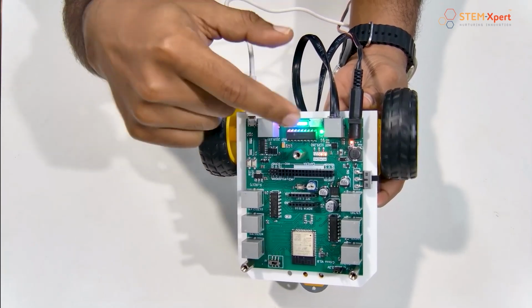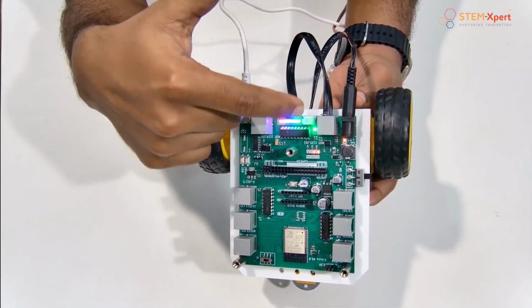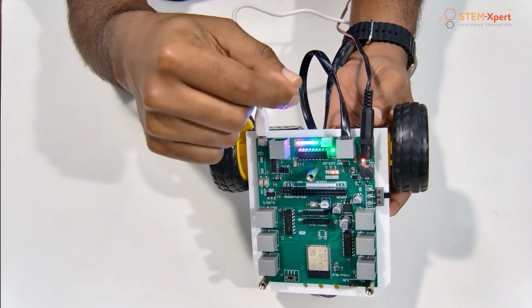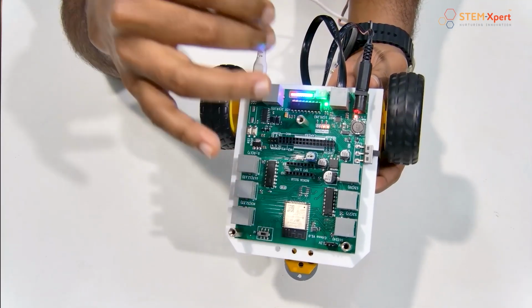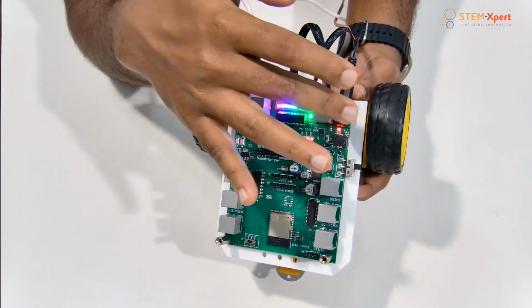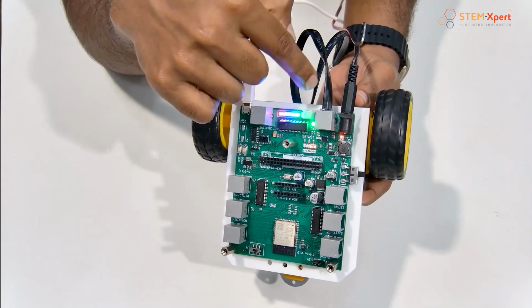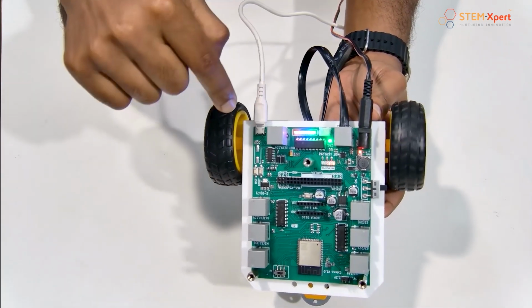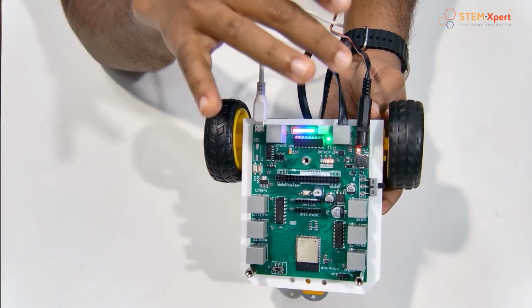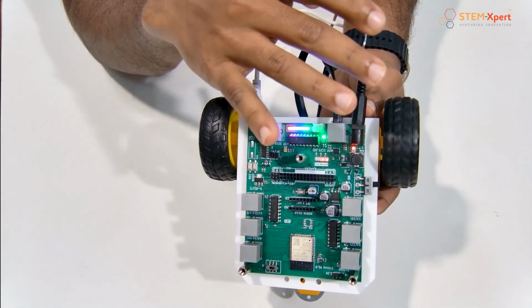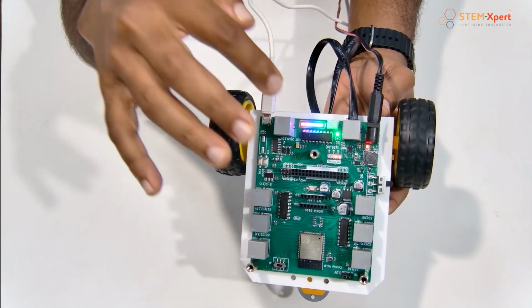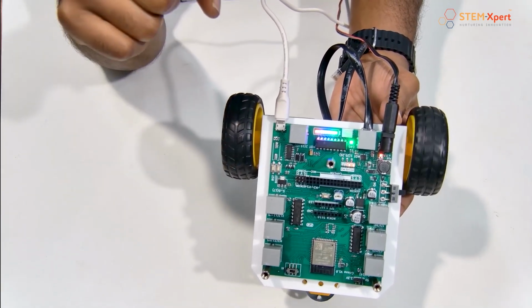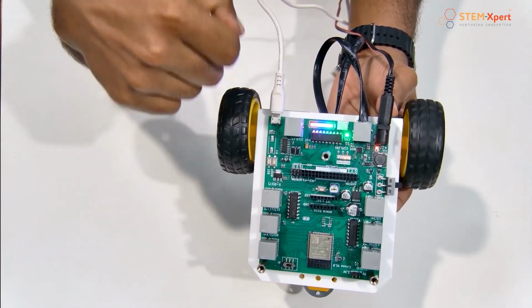So in the same way, what we are going to do is we are going to make use of the other pins. So the other pins are 26, 19, 15. So 25 and 26 pins are used for this motor. So we need 2 pins for each motor. So we will get 25 and 26 pins for this motor and the 19 and 15 pins for this motor. So we will use this motor to work accordingly.